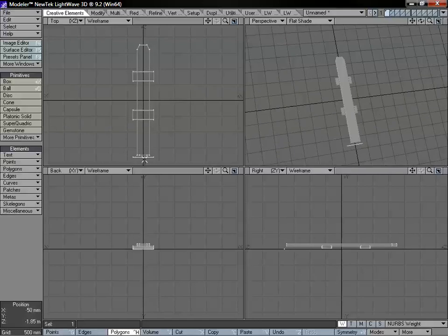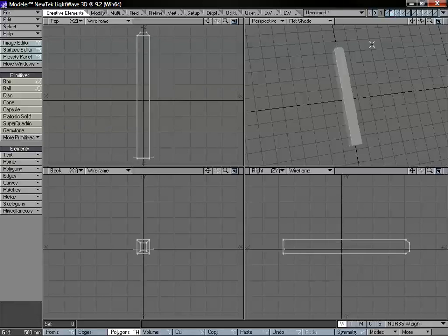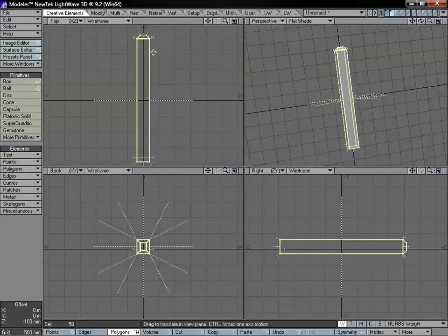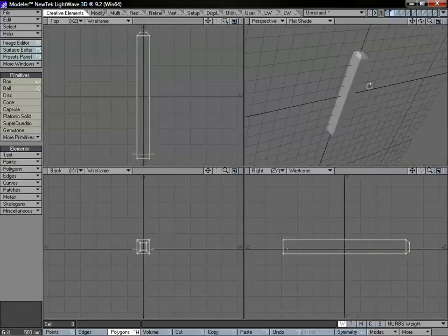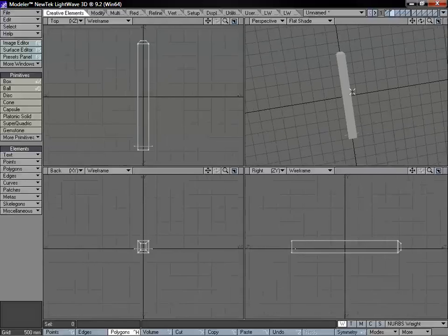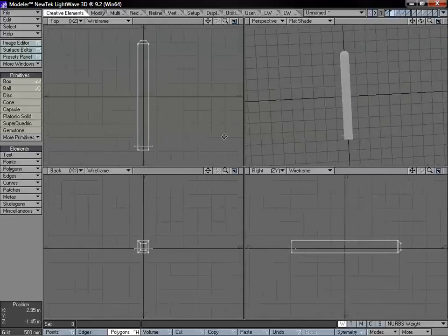But I'm going to keep this the way it is right now and select the poly that we had created, or our curve, our 2-point curve for our fence section. Copy that and paste that onto our post layer. I also have this line a little bit above the post so that if we wanted to, we could have that going in the ground. And I am actually going to move that down just a little bit further. And if we were going to be working with a very uneven terrain, then you might want to customize your posts to go just a little bit further than that.